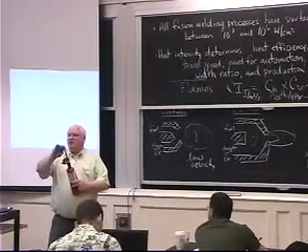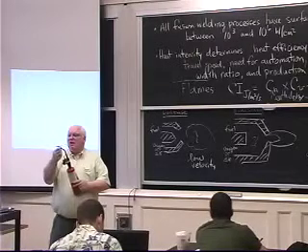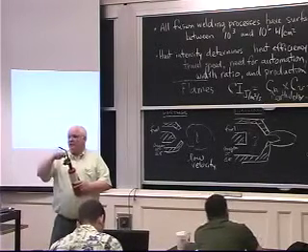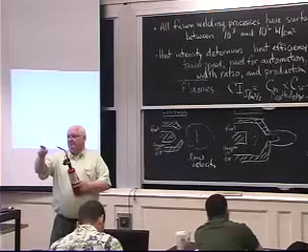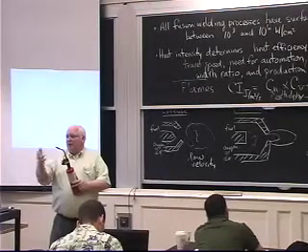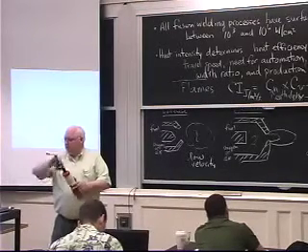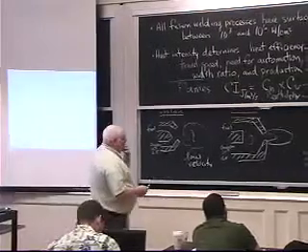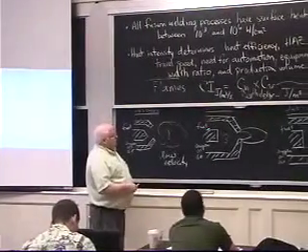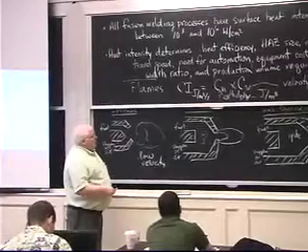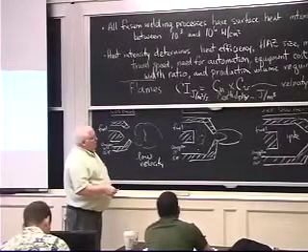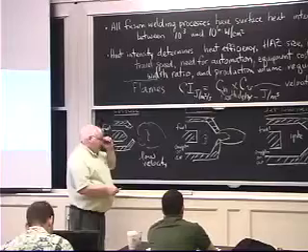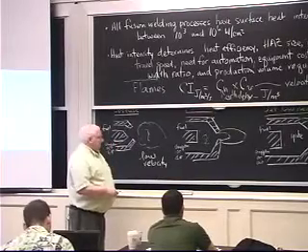It mixes in here, but it doesn't burn until it gets out, as long as I've designed the whole thing so that the burning velocity is not greater than the exit velocity. Okay? If I don't design my torch with the right size orifice and air holes and everything, I won't get a good mixture close to the correct mixture of fuel and oxygen. But if I do, I'll have mixing of the fuel and the oxygen inside a chamber at essentially constant pressure.